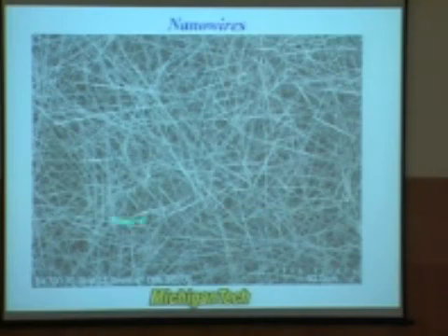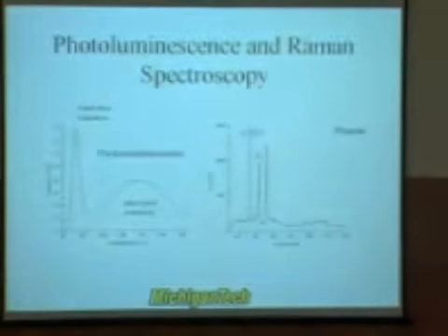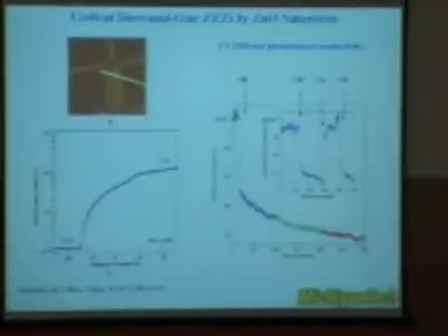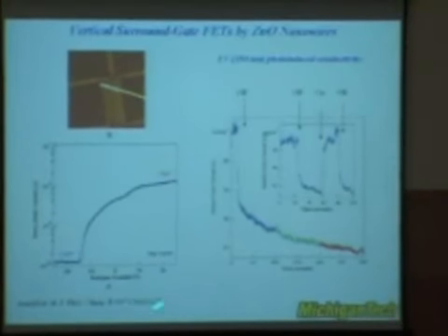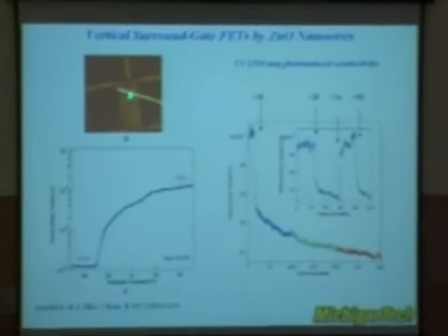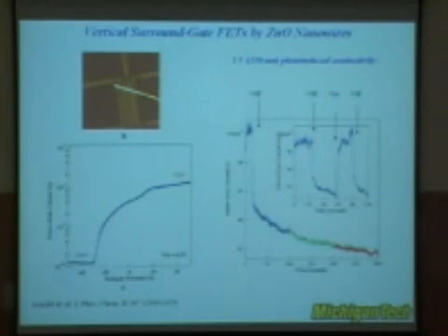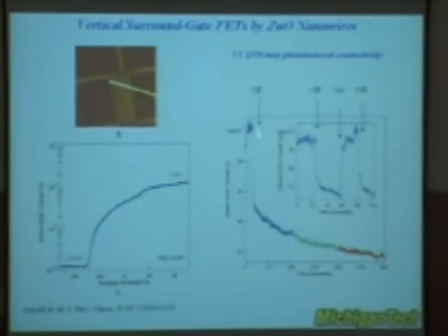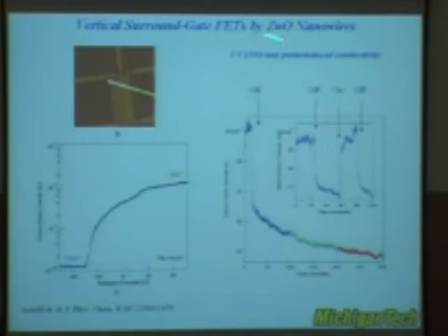This one is grown at 500 degrees Celsius. Absolutely compatible to the CMOS technology. You can directly grow them across the electrode if you want. All right, just skip some of them, and actually already demonstrated in year 2003 using a piece of nanobelt, which demonstrated the on-off state. And also, it can be used to sense UV light, actually.